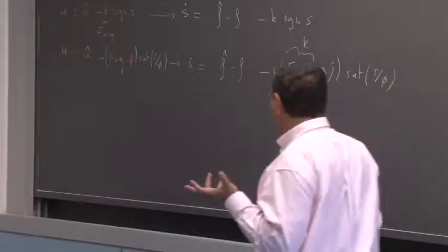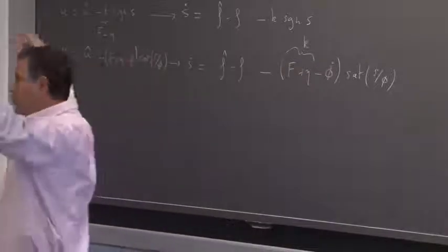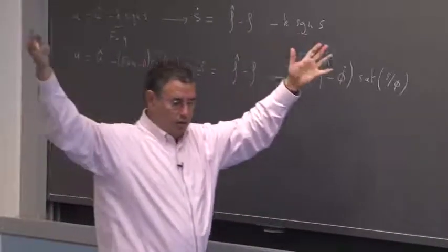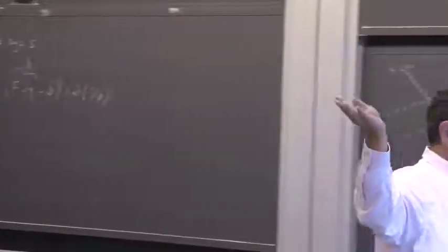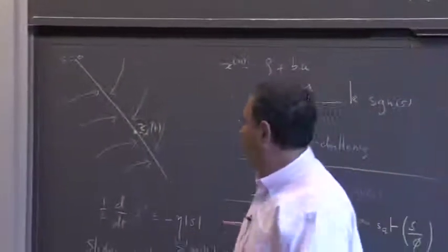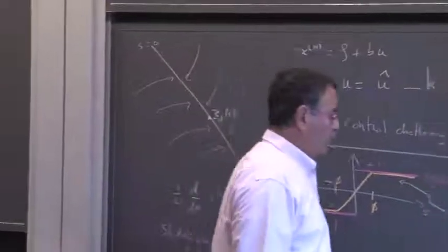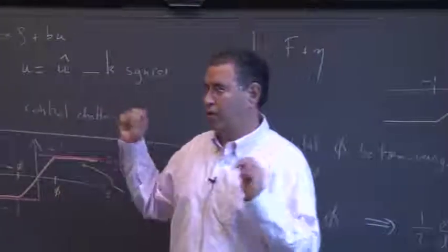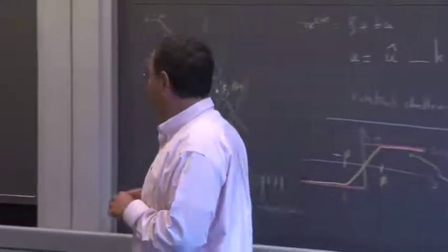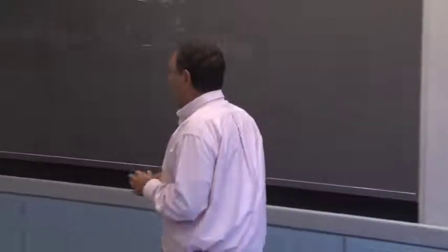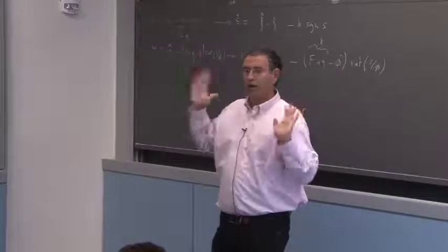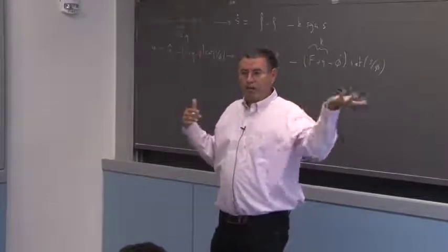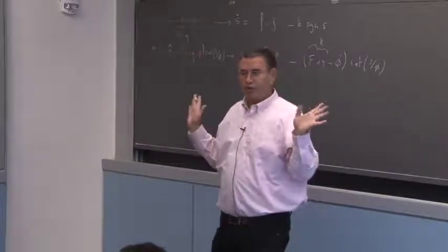So let's now start somewhere outside the boundary layer. We reach this boundary layer in finite time because we made sure we included this phi dot term in the gain. And once we're in the boundary layer, although it might be pulsating, we've guaranteed because of this phi dot term that we stay in the boundary layer.